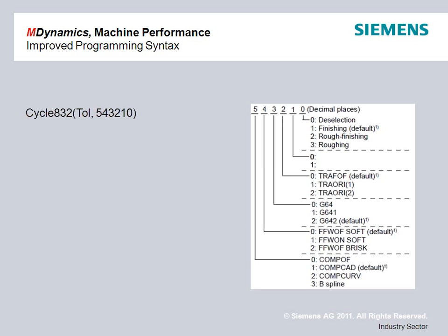There are very, very few machines where that's a decision that's made in the part program. Either the machine is configured for feed forward based on its servo optimization, or it's not. You would only typically use one of them. Typically, the way most people set up machines, those are hard-coded, and the commands are ignored anyway. So instead of having to make you guys, as the end user, remember to keep putting in these things that we're going to ignore, the new simplified call is good.